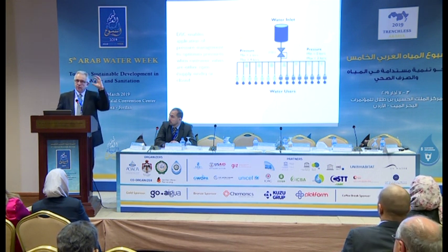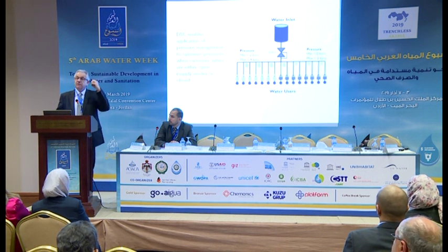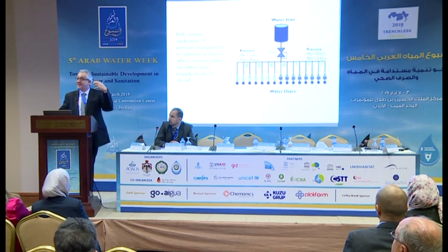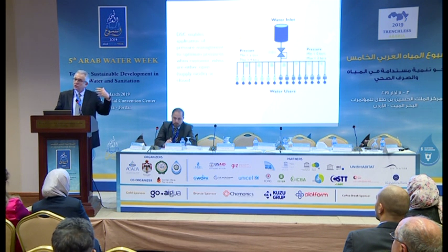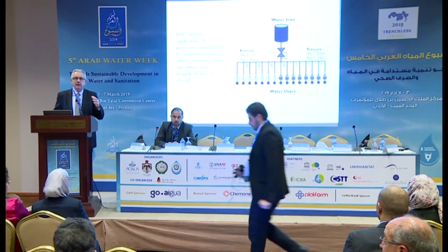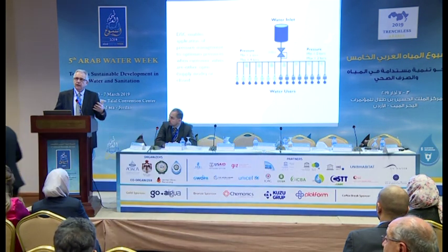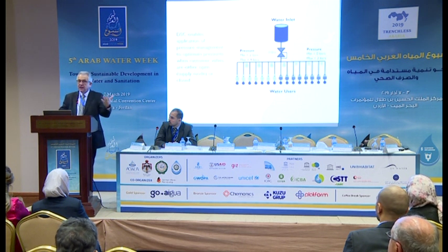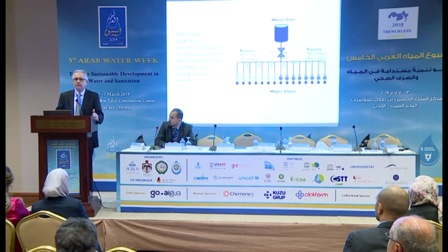What can we do as a utility in order to improve the situation? So we have control, bear this in mind. We have given our customers the volume of water that supposedly they were getting under intermittent water supply, but we will be giving it in a more efficient way. We could actually control the volume that we give to each customer so that there is some kind of equity.